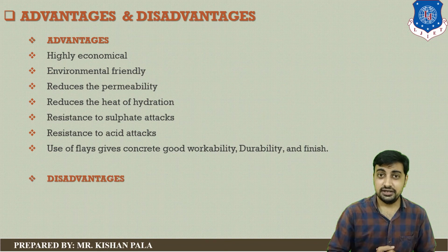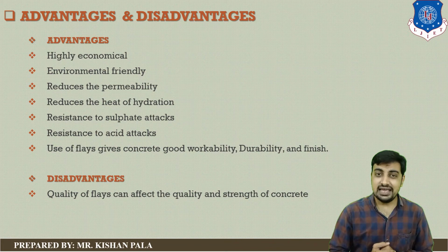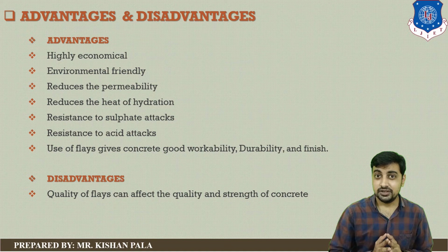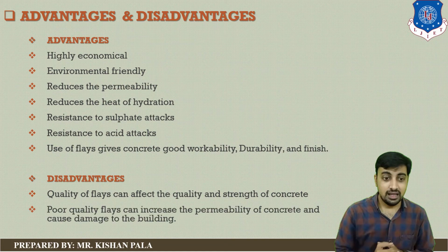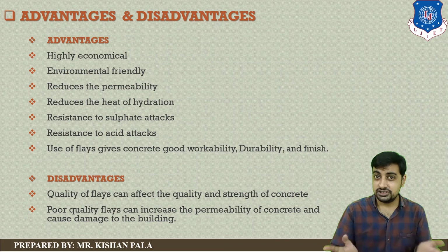Let us discuss disadvantages. The quality of fly ash can affect the quality and strength of the concrete. This is the main disadvantage. Poor quality fly ash can increase the permeability of the concrete and can damage the building or any type of structure.